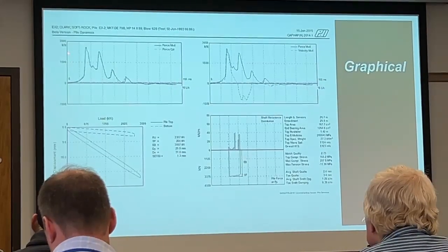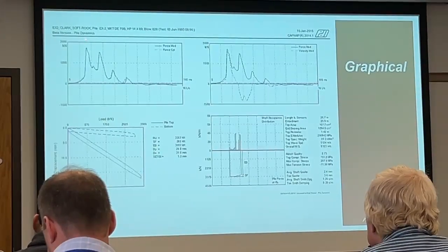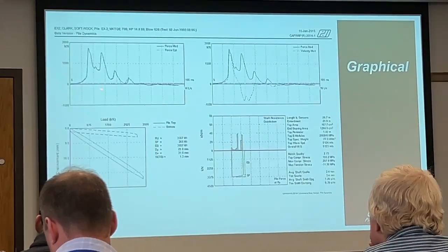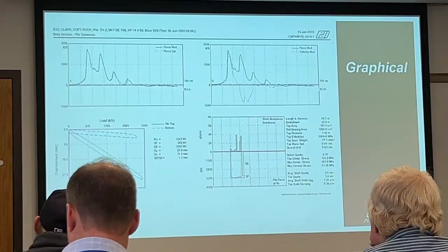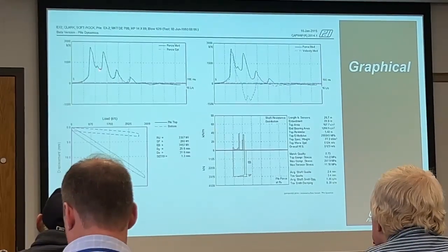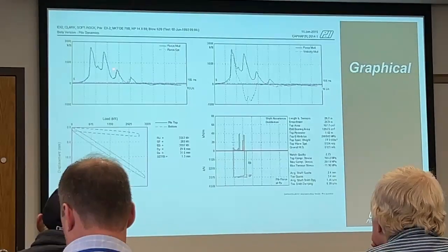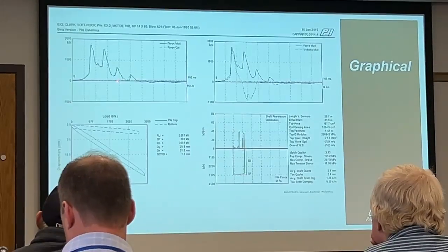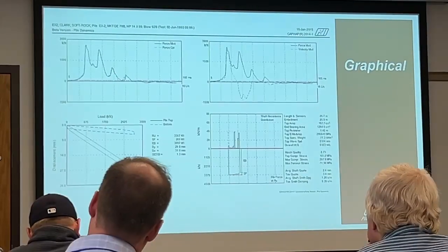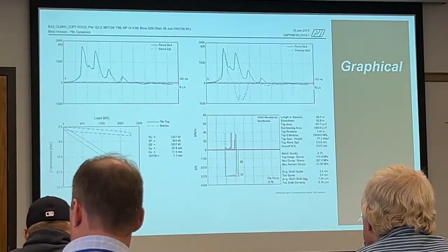There isn't a scenario where the computed force is way above the measured force, especially between the impact and about 4L over C. That's telling us that things are pretty good in that sense. And then out at the end, we see some slight differences.